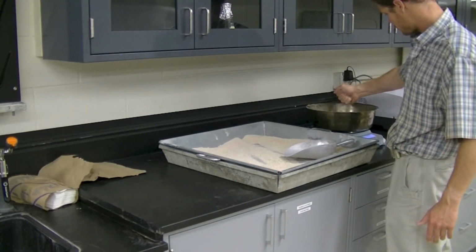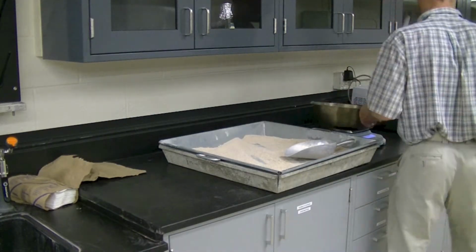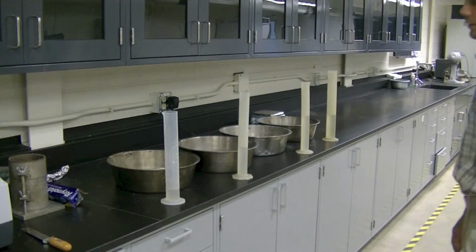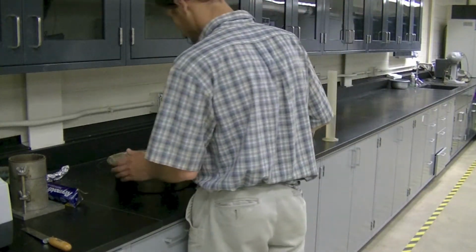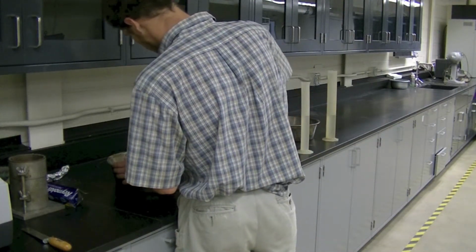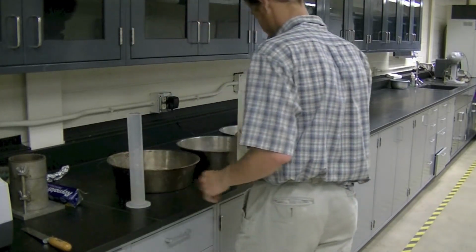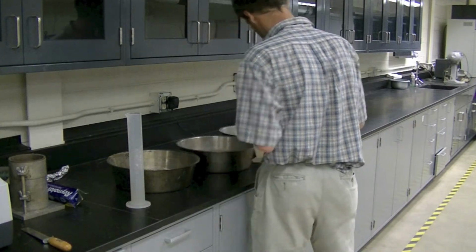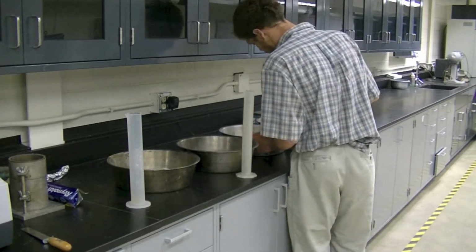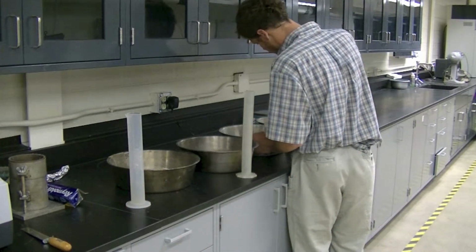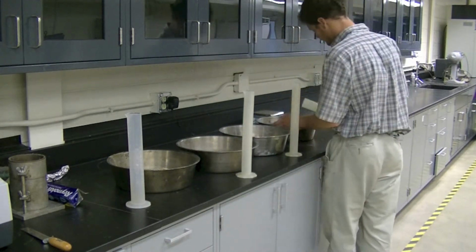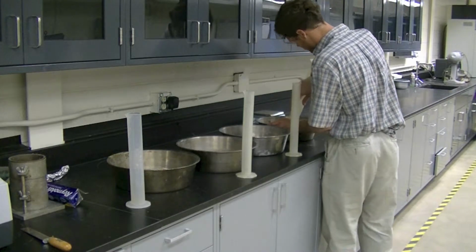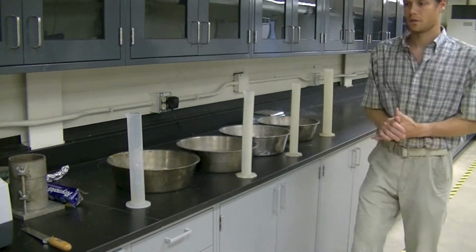Estimate the general water content of your soil by squeezing a small amount. The goal is to bracket the estimated water content within the 4 trials. Select the molding water contents for the subspecimens such that 2 subspecimens are dry of optimum and 2 subspecimens are wet of optimum. Molding water content should vary by less than 2%. Generally for a 5-pound sample, this means that the increment should be 50 milliliters. Since our specimen was fairly dry, we added 100 milliliters to our first, 150 milliliters to our second, and so on.